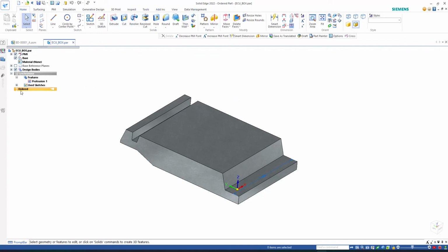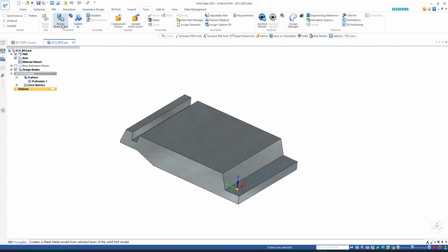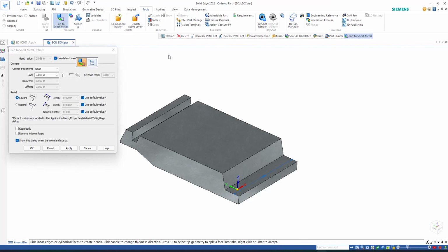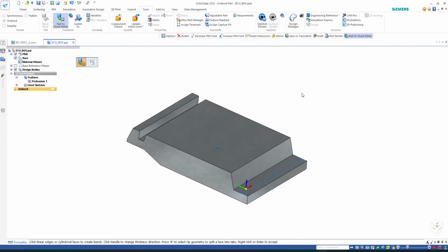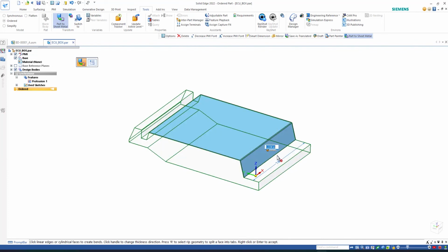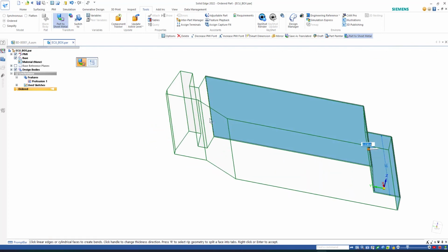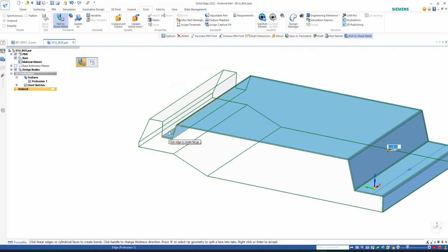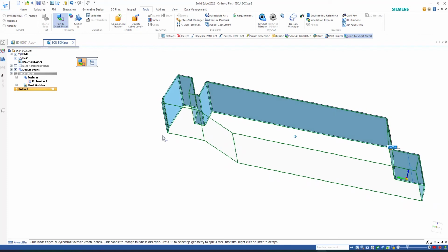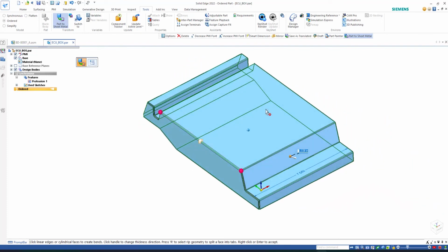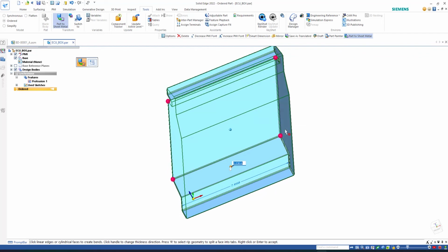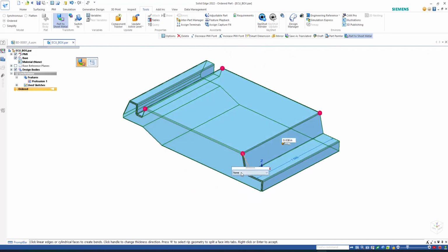And you have to be in ordered. So you need to go to Tools, see Part to Sheet Metal, select the command, and say yes, select the defaults there. At this point, simply start selecting the edges. You see how it started to place in the sheet metal there. I'm going to come back and just work my way out there, all the way to that one right there, and then come back and do these side ones here. If you click on these little glyphs here, see how it gives you options to open, close. I'll leave the default, and then accept that.